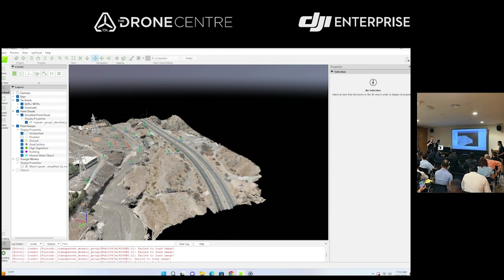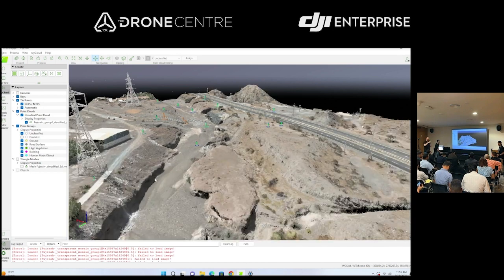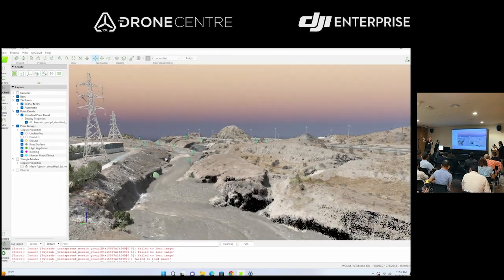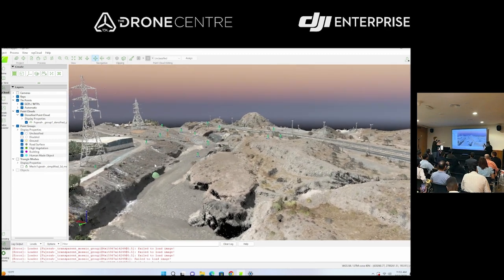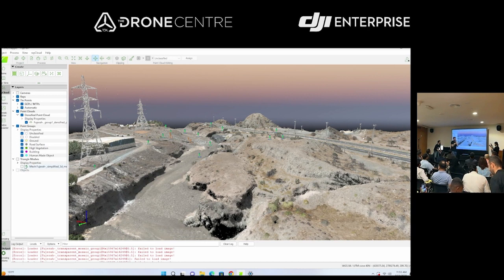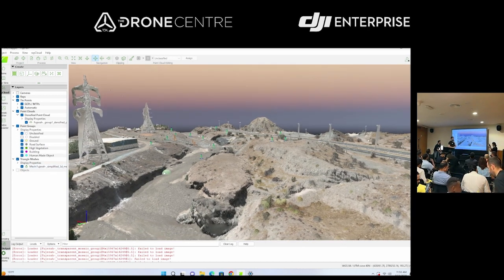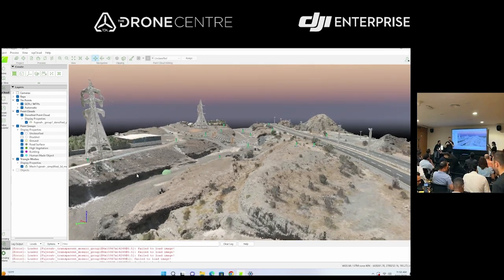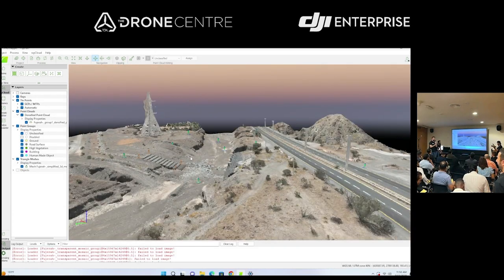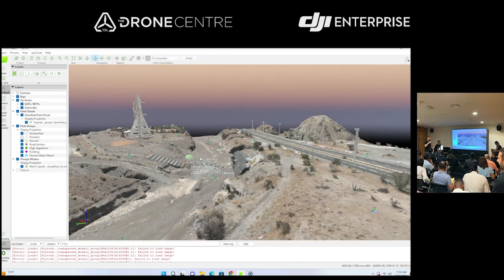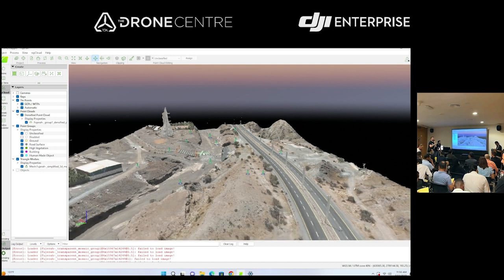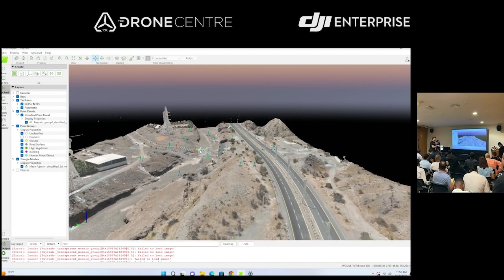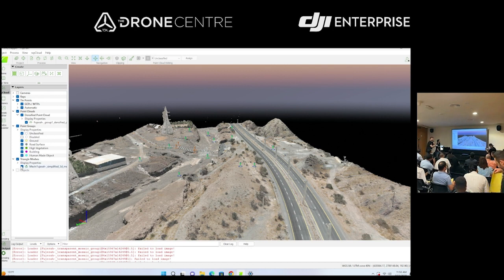When you're operating a Mavic, this is the exact scenario that I was asking about. With the Matrice 350, you can attach the CSM radar, so that will detect these power lines, and you could go full stick forward, and it will not fly into that power line. It's there as a safety net, but many operators fail because they use collision avoidance as a tool they always use. It should be the last case scenario. It's there to protect you, but don't use it as a method of approaching a scenario. You don't want to go full stick towards the power line. There may be a scenario that prevents it from operating.